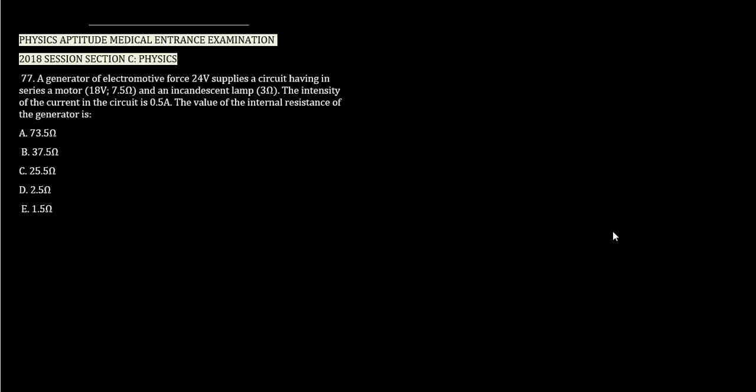Okay, so we are going to proceed with question number 77. A generator of electromotive force supplies a circuit in series, a motor 18 volts and 7.5 ohms, and an incandescent lamp 3 ohm. The intensity of the current in the circuit is 0.5 amperes. The value of the internal resistance of the generator is...